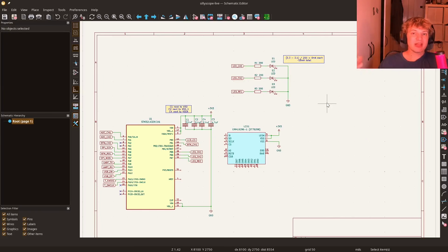We're missing something incredibly important at the moment, which is our power input delivery pipeline. We've decided that we're going to have a 3.3 volt rail, but where does this even come from? Well, we've already decided in our requirements that this thing is going to have a USB connection. So knowing that USB gives us 5 volts, we can start with a USB connector, and then we can add a voltage regulator to scale that down to 3.3 volts like the rest of our circuit is desiring.